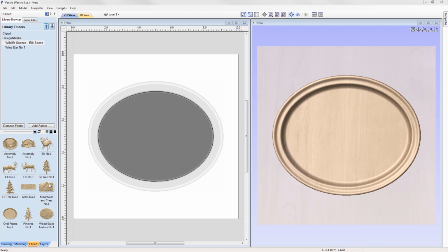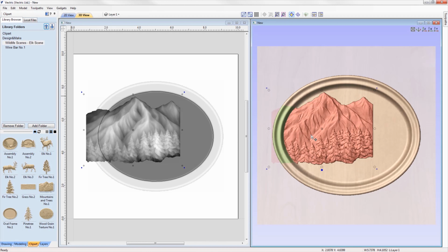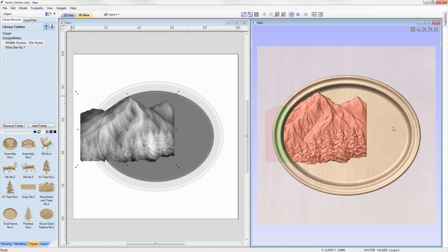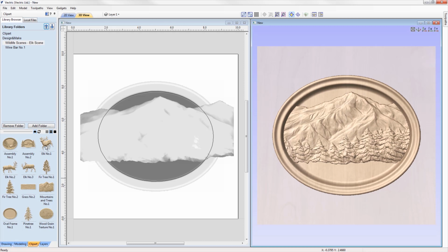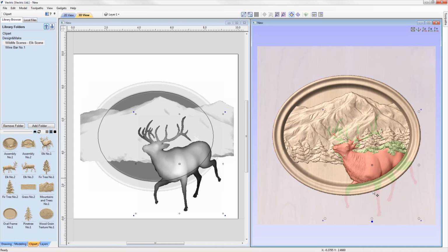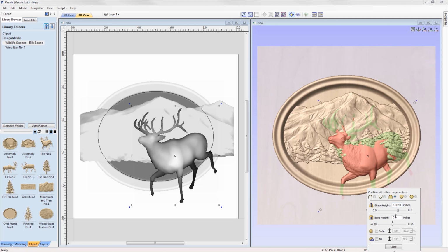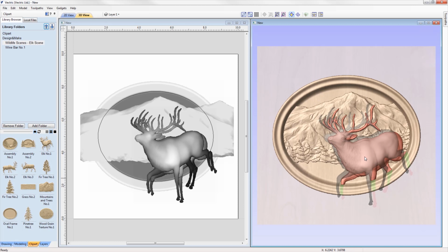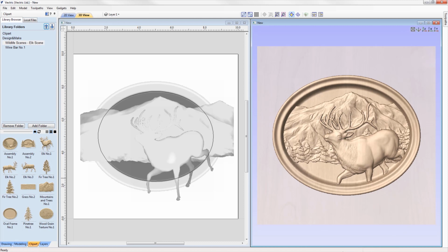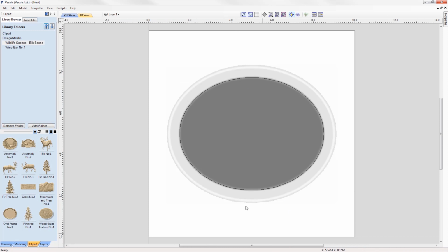We've added a new property to the levels in the Modelling tab, where you now have the ability to clip components to a vector, giving you more scope when creating assembled layouts in the software. When this option is enabled, the level will be constrained to the chosen vector without affecting the underlying components. You can rearrange components and modify the underlying design, and the results will be dynamically clipped away in the composite model without actually cropping the component itself.